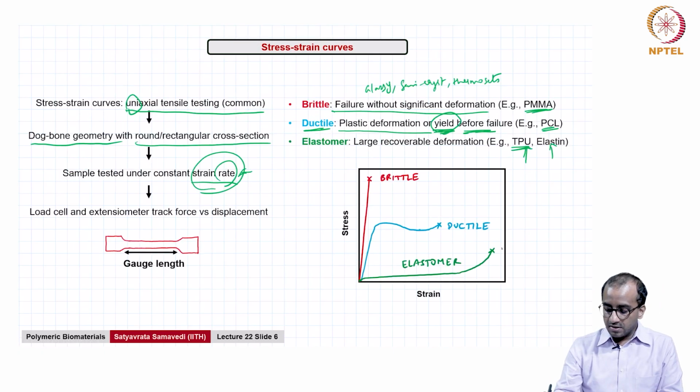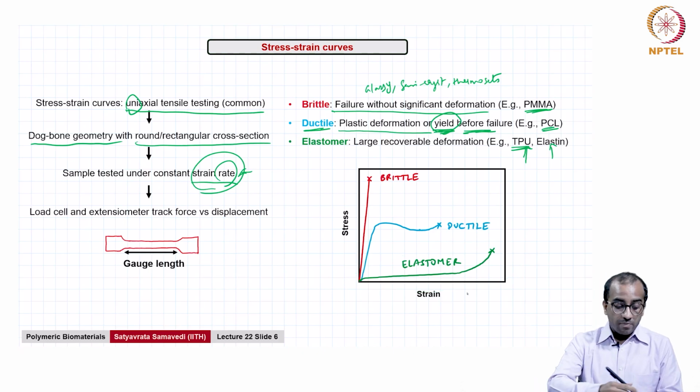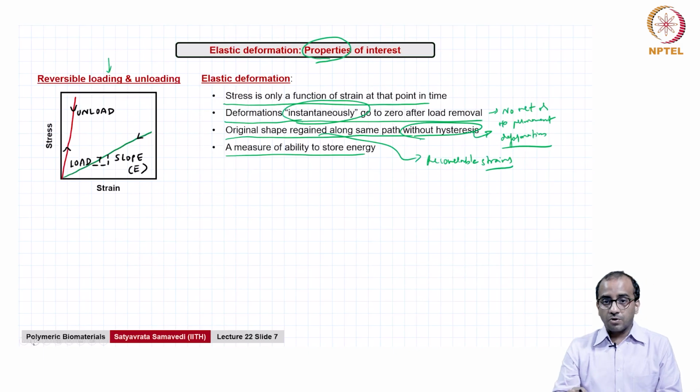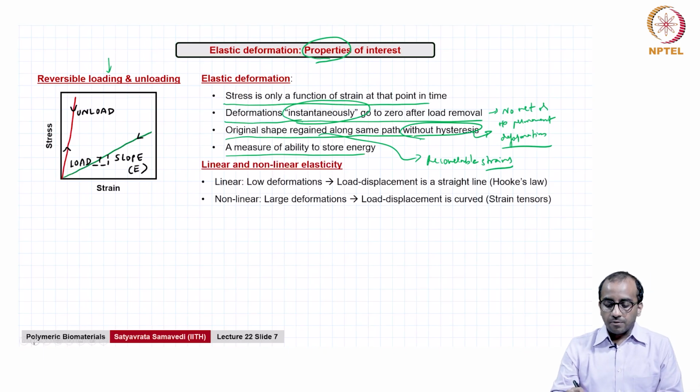You see this curve here. If I keep stretching, the response is not fully linear throughout. For very large deformations particularly, I see non-linearity. But then the contention is it can still go back to 0 once the load is removed, right. So, the point we are trying to make here is that elastic responses need not simply be linear, they can also be non-linear, and that point is reiterated here. You can have linear and non-linear elasticity.